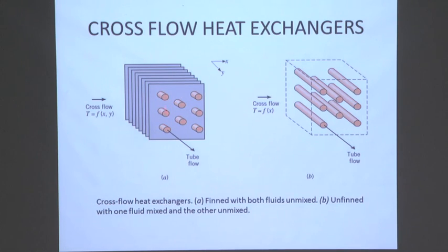I will tell you. The arrangement is like that, these plates act as fins to all these tubes. So through the tube one fluid flows, and heat exchange from this fluid to the outer fluid is enhanced by these fins, whereas the other fluid, that is the outer fluid, which flows through the finned passage, is a cross flow type through this finned passage.